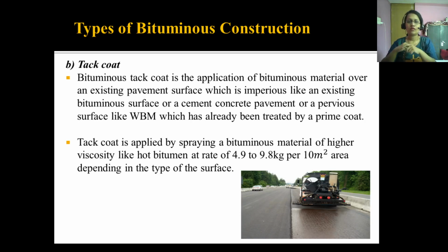Then we have the tack coat. Bituminous tack coat is the application of bituminous material over an existing pavement surface which is impervious, like an existing bituminous surface or a cement concrete pavement, or a pervious surface like WBM which has already been treated by a prime coat.